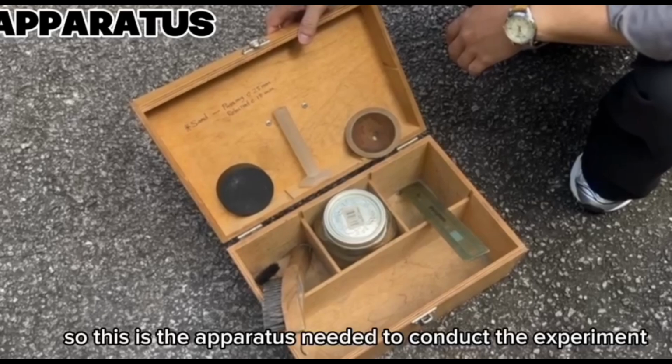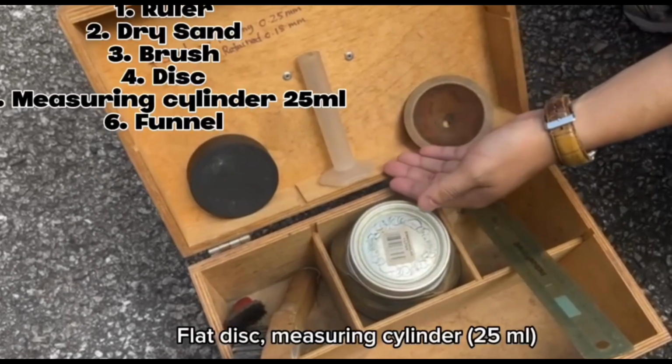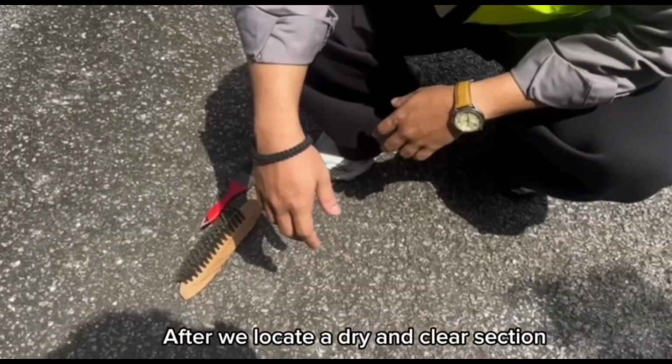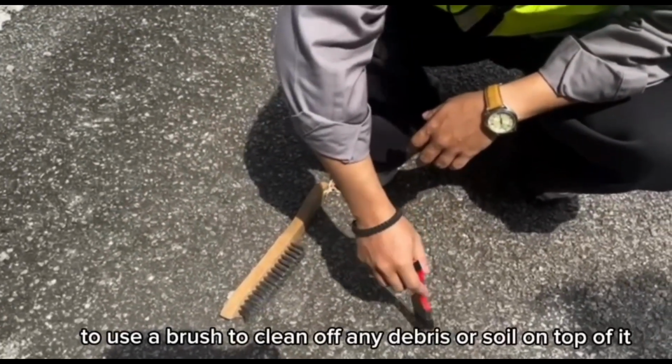So this is the apparatus needed to conduct this experiment. First we have a ruler, dry sand, 2 types of brush, flat disc, measuring cylinder, 20 ml, and funnel. After we locate a dry and clean section of a pavement, we need to use a brush to clean off any debris or soil on top of it.